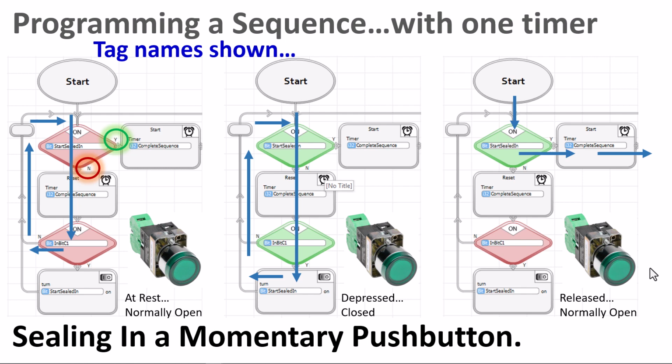All this is how do we press a button to start something but have it continue. In other words, we don't want to hold down the button, and we don't want a switch where you just switch it on, like a selector switch, like a light switch. We want to press a button and have it run and not hold the button down.